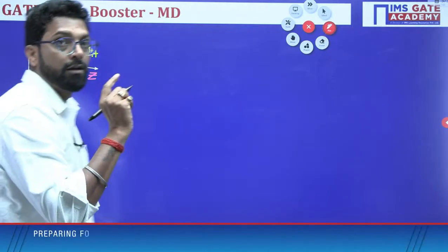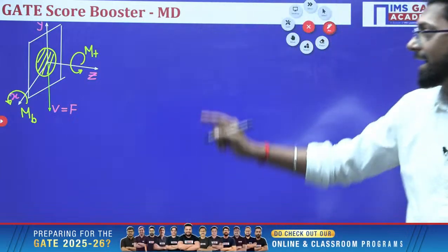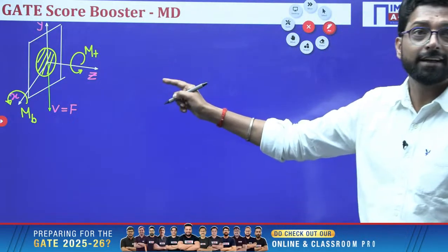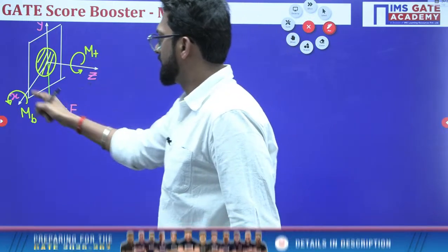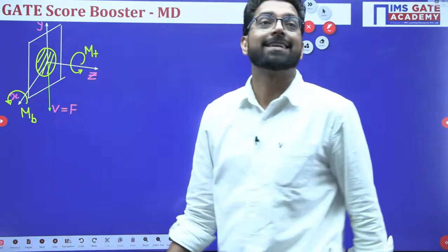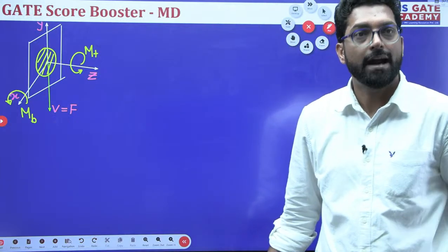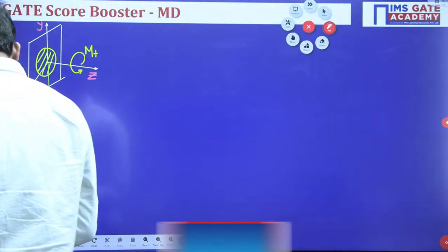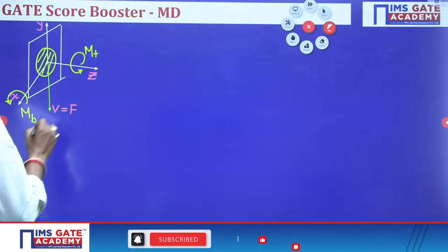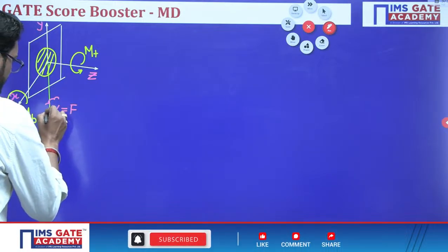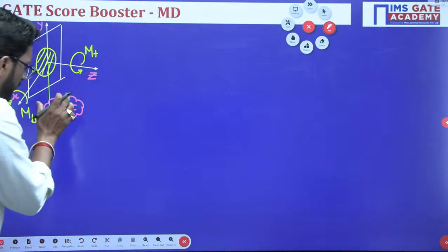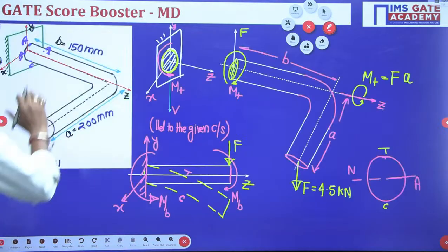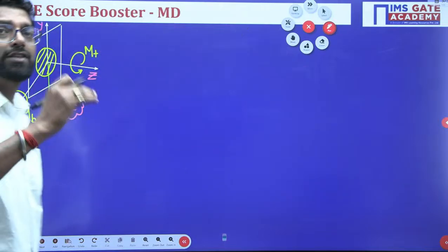Clear? At the base, what is the loading condition? So these are the loading. These are the twisting moment, these are the bending moment, and these are the direct shear stress at the base. So see, what is this one? This shear force will produce a very low effect. In this geometry, the shear force does not affect much.